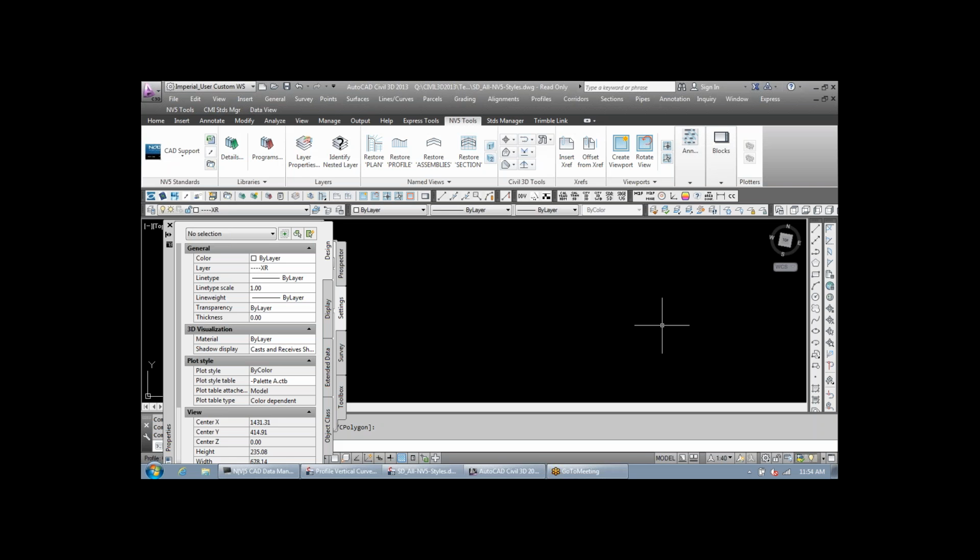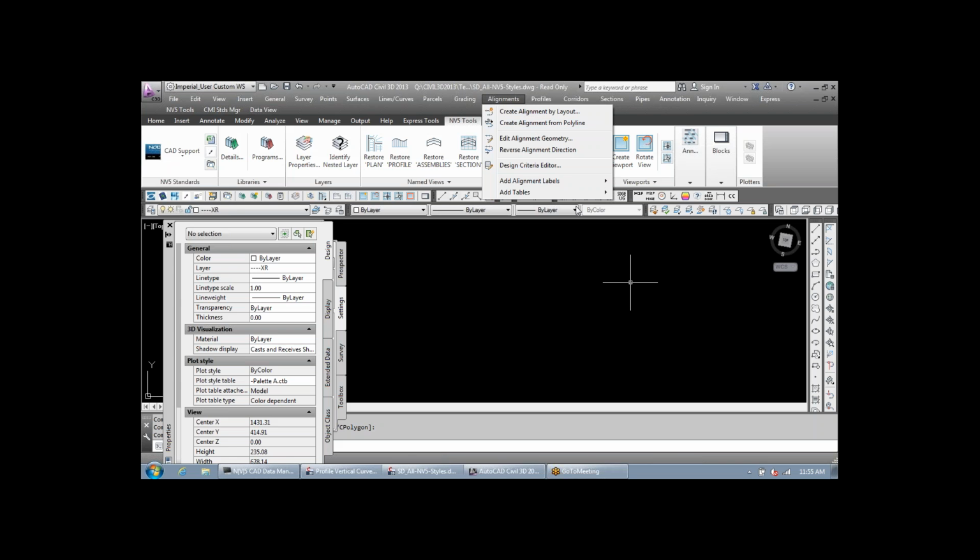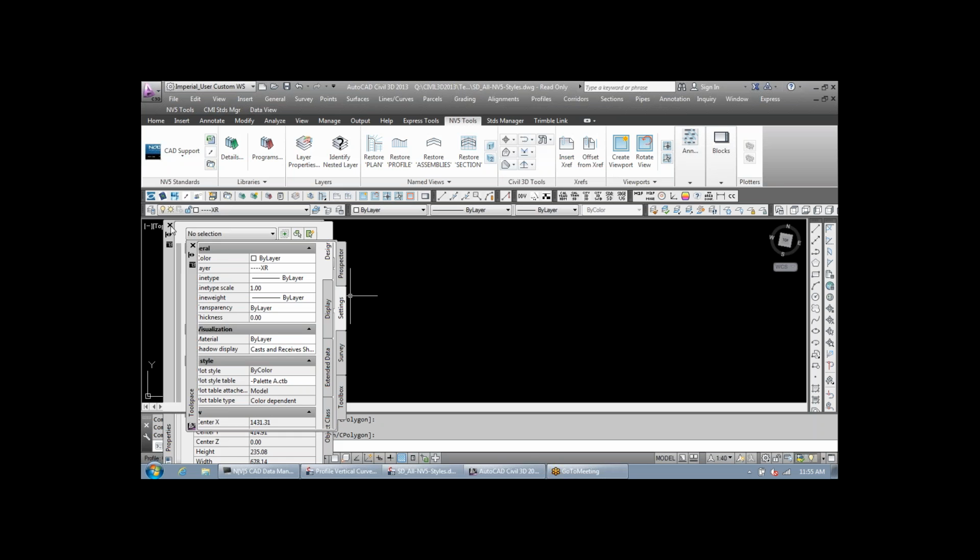There is a Civil 3D automated workflow to kind of have that plot in all your section views. It's very helpful. The best way of doing it is I'll just briefly tell you the workflow. I won't demonstrate it, I'll just kind of talk through it. And if you encounter this in a workflow, I can kind of help you out a little bit. But let's say you want to have your right-of-way show in all of your section views. What you do is you'd create an alignment on top of your right-of-way. And then what you do is you'd go under to alignments, sample, okay, under your tool space.